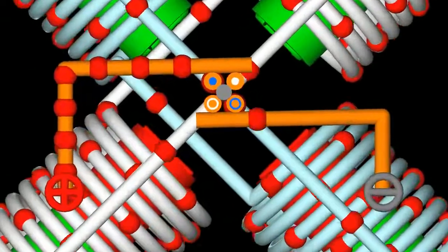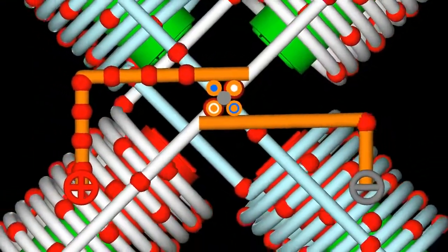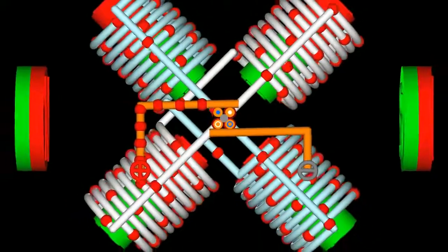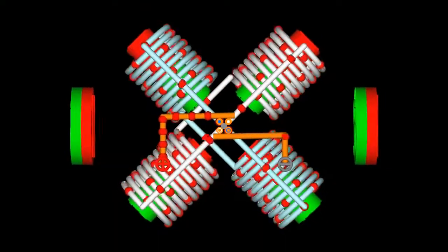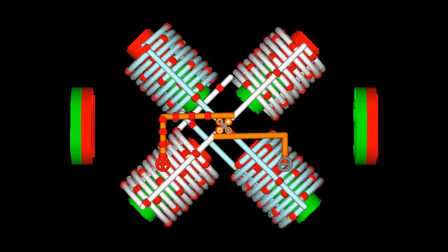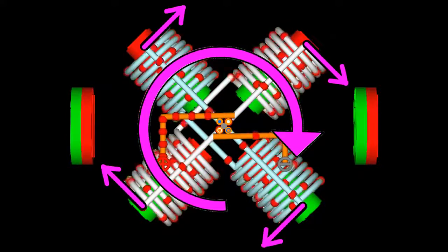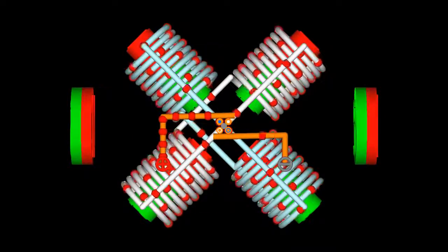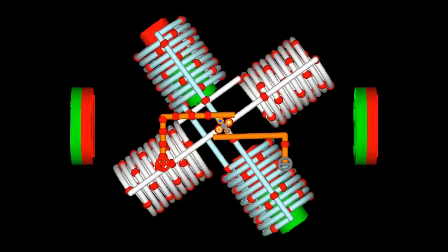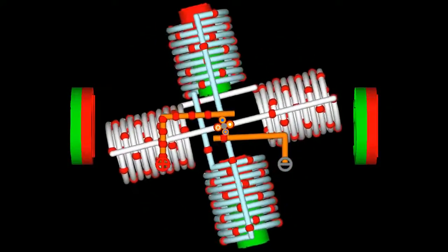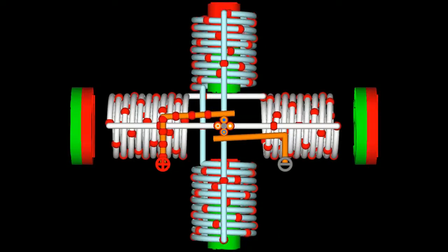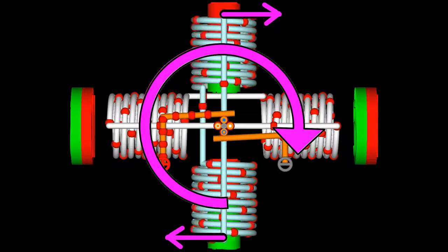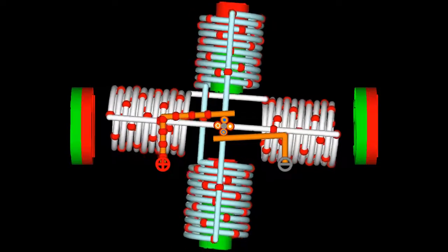After 45 degrees, the light blue electromagnet makes contact with the brushes. Consequently, a magnetic field is established with the north pole pointing to the top left. The torque acting on each electromagnet points clockwise. When turned a few more degrees, the commutator breaks the contact of the white coils and the voltage source, thus that magnetic field disappears. Nonetheless, the forces caused by the magnetic field of the light blue electromagnet still point clockwise, making the motor continue to spin in that direction.